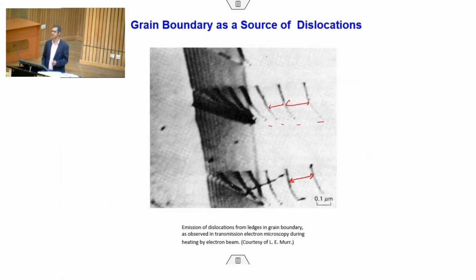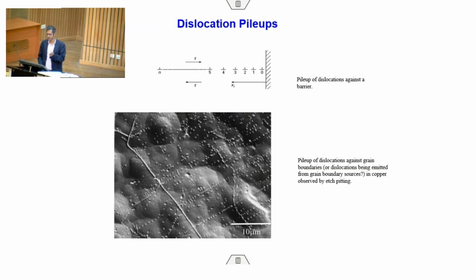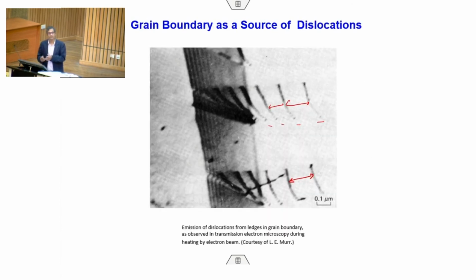Now, strain means there will be a stress field around it, and the stress field will not allow two dislocations to come as close as possible. If the stress fields overlap, it will lead to an increase of energy, and many things can happen. It is not possible to have two dislocations coming closer than a certain distance. In fact, the distance can be calculated knowing the stress field, the Burgers vector and many other things. So, the dislocations generated like this are moving inside the grain.